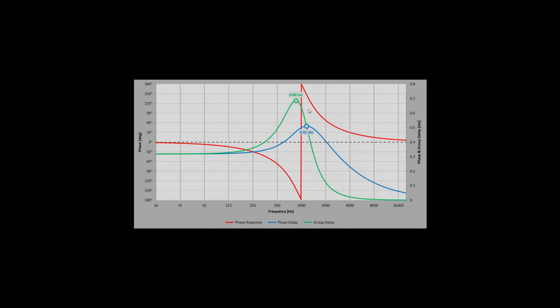What you should remember from this graph is that this is a crossover causing a phase shift at 1000 Hertz. And look at the group delay it introduces. So when you apply the opposite, the time-reversed version of this crossover phase shift, as a filter linearization, you apply the reverse of this group delay. So you literally decrease the group delay by 0.69 milliseconds at around 1000 Hertz. And group delay is one of the hardest things to get rid of in any digital correction. So this very simple correction with no frequency magnitude correction involved gives a much cleaner sound overall, because it gets rid of the group delay as much as it should.